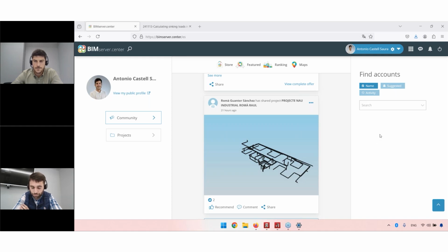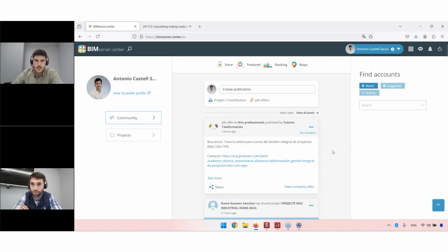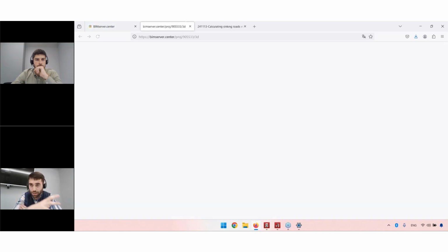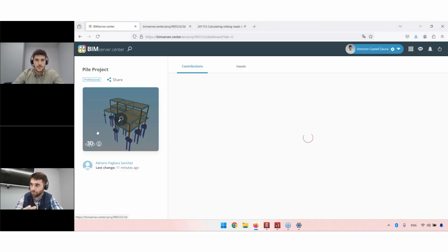For the second module, we're going to have the verification of the reinforcement that is introduced by the user into a pile, for example, also the pile cap, as we have shown before, it is already verified. But now this feature is going to be advancing onto the piles. The user is going to define the bars there, and the verification is done with a minimum momentum that is also going to be introduced by the user.